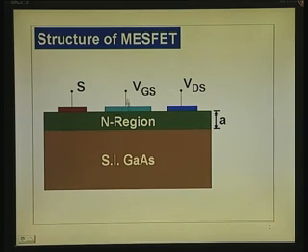And if this metal semiconductor, that is, if you apply a plus voltage with respect to the source ohmic contact, that is a forward bias junction. If I apply reverse bias, that is VGS is negative, that will be a reverse bias junction. So, I am just using the term VGS.